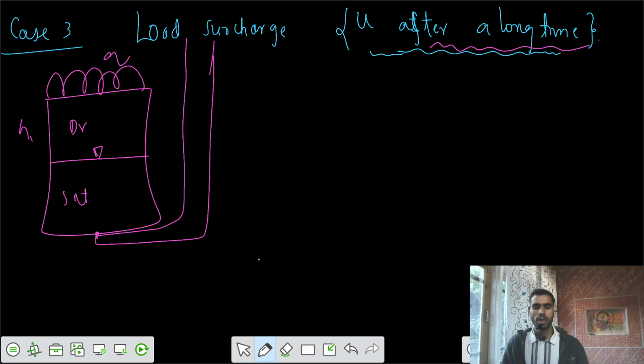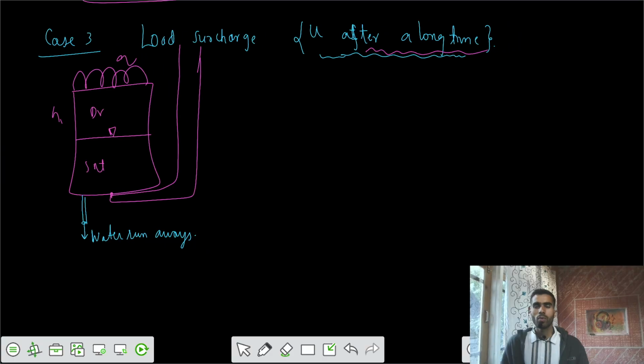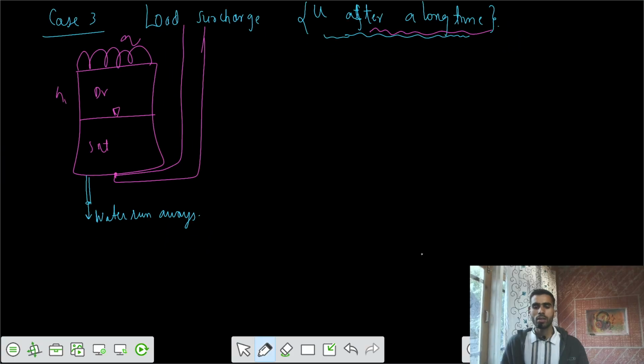What did we say in the first case? In case 2, we said that there would be some loss of water. Water runs away towards the drainage face. To resist that increase of Q, water has developed a stress, U excess, equal to Q. This was the immediate condition. Now water wants to relieve that stress.